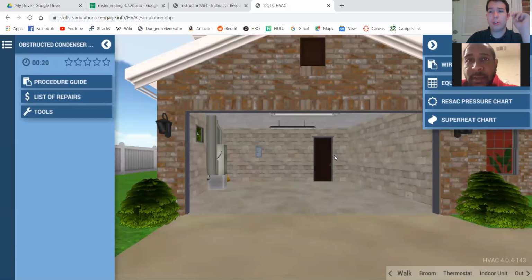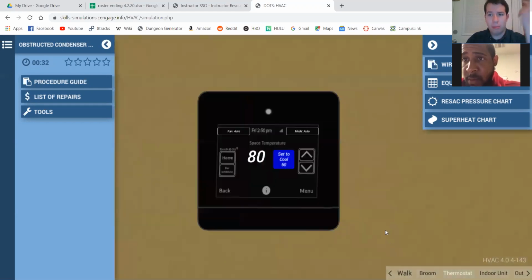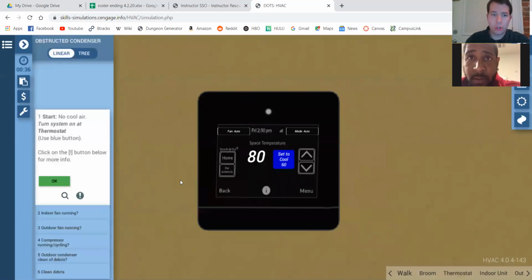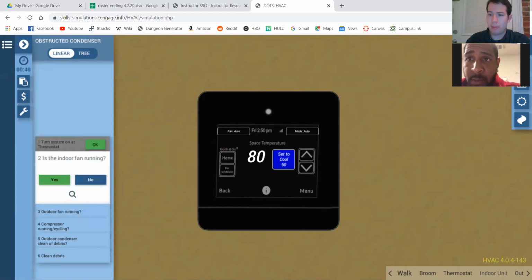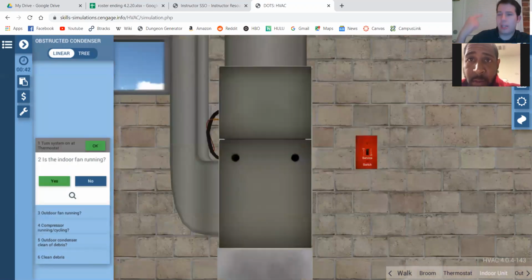We always go to our control system on any call. Residential, refrigeration, commercial, industrial, we go to our controls. And that's where we start, because that's what should tell the system what's going on and off. So for our controls for residential, it's always starting at the thermostat. Always turn that puppy to cold, say, all right, let's get the AC going, let's get that fired up.